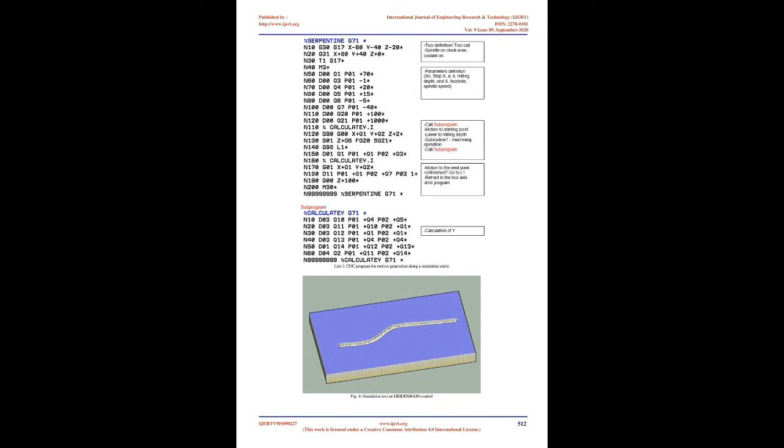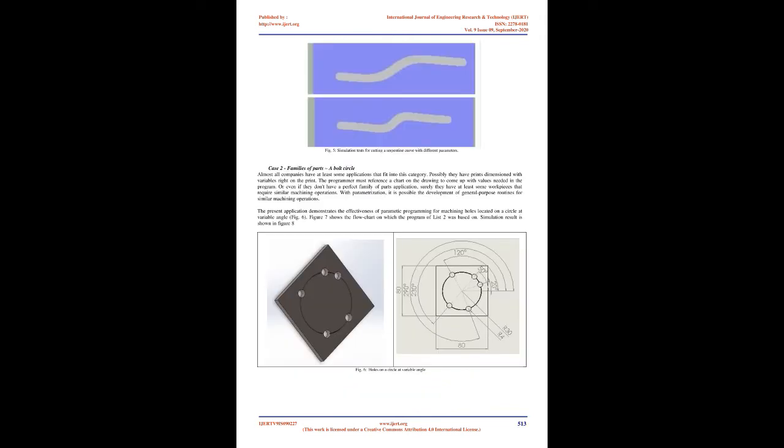While CAM systems have come a long way, it can be difficult, if not impossible, to cause some CAM systems to output CNC programs as efficiently as can be done with parametric programming technique. Applying the technique of parametric programming, a part program can be written using variables, arithmetic, and logic statements similar to usual programming languages such as BASIC, Pascal or C. The specific is that in the case of CNC programming, all these parametric expressions are used to represent the machine axis position, feed rate, and spindle speed functions.